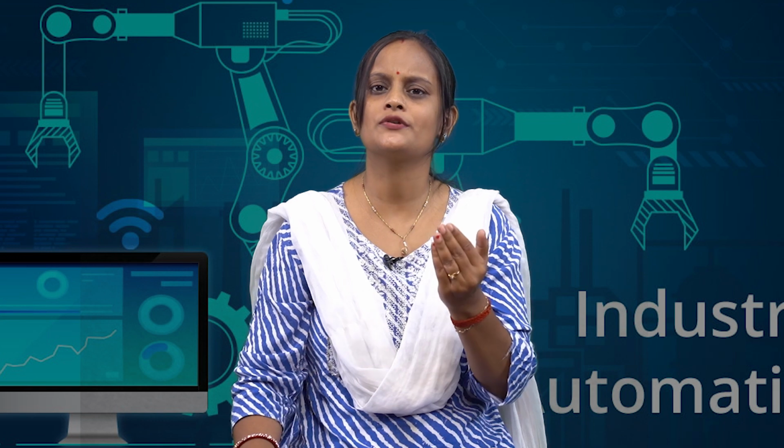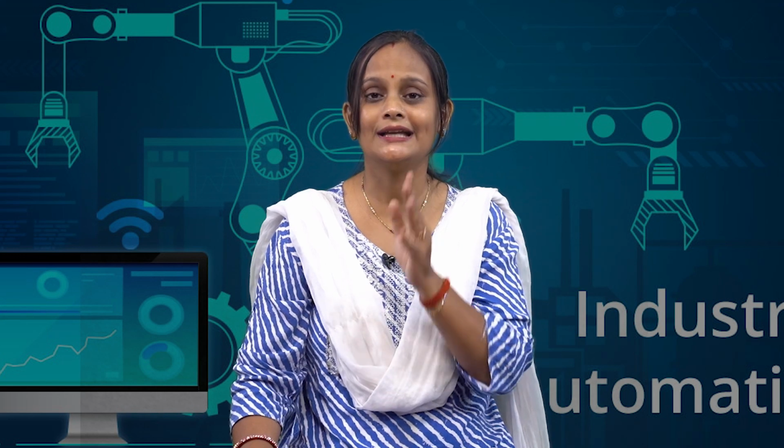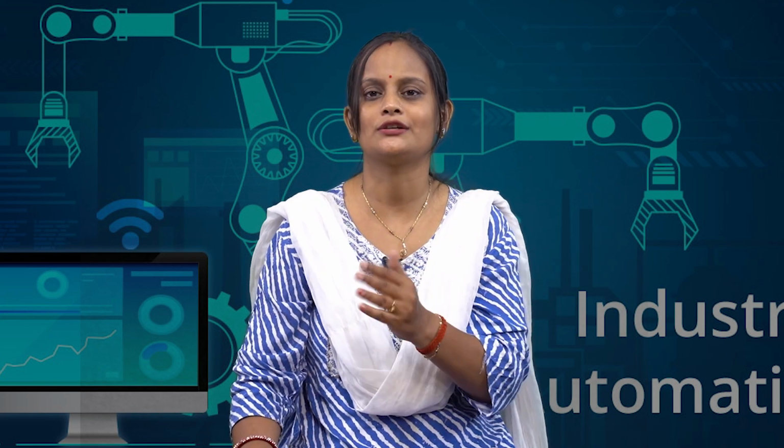Okay, so it is just the opposite of the AND. In the AND, if 1 1, then Y equal to 1, else Y equal to 0. In the NAND, if A is equal to 1, B is equal to 1, then Y equal to 0, else Y equal to 1. It is just the opposite, the NOT of the AND operation.